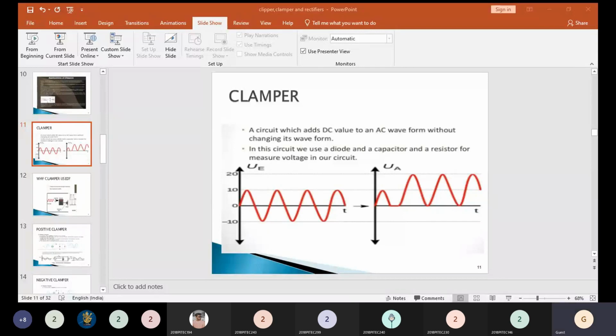So first you calculate your AC voltage. First you calculate VM and then IM. What is VM? VM is nothing but root 2 into secondary voltage, right? 50 voltage is given in the question. So 50 into root 2 is equal to 70.7 voltage. Okay, next one is what?